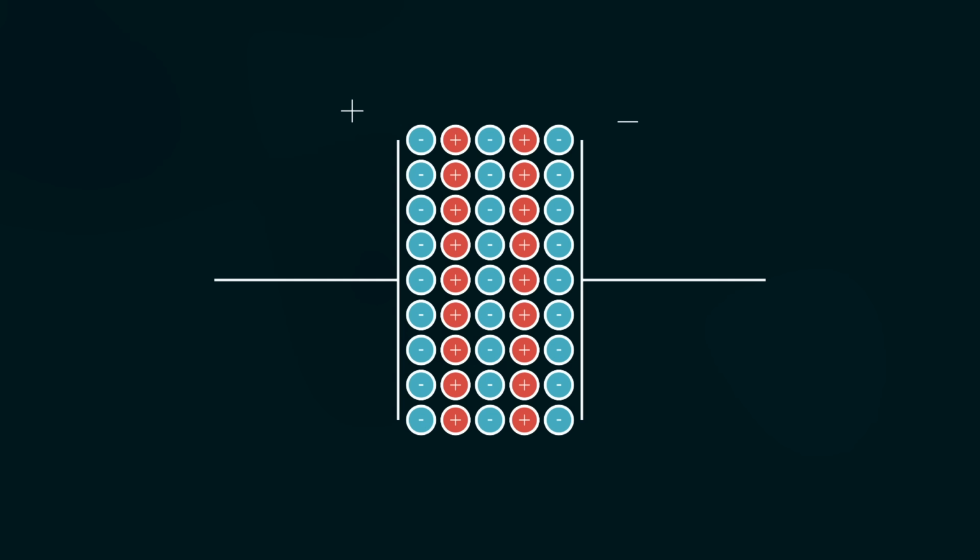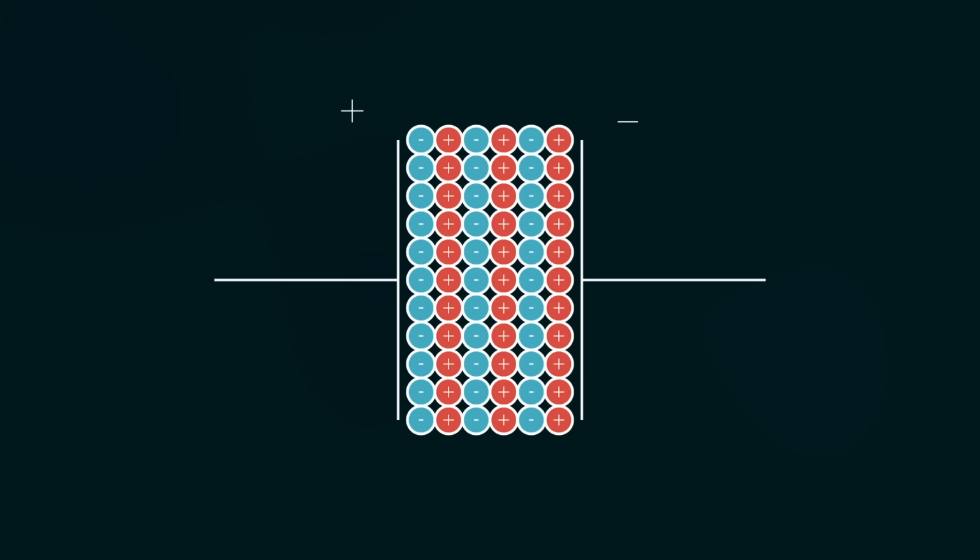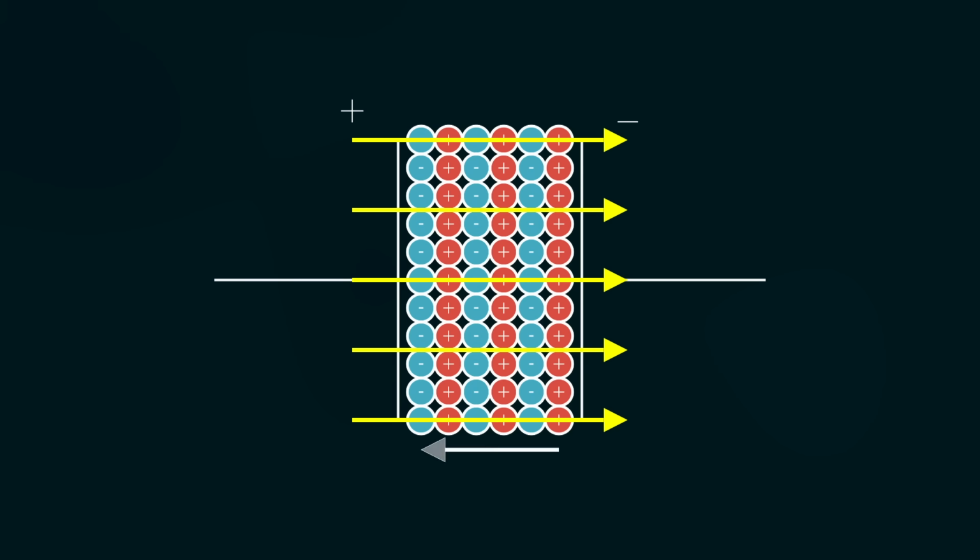While it can't conduct charges, the atoms can reorient themselves, which means they'll take this configuration since opposites attract. On the inside of the material, the pluses and the minuses cancel, but on the outside, you get a small electric field pointing like this, opposite the electric field from the capacitor. Since the voltage is derived from the electric field, a weaker electric field means less voltage.